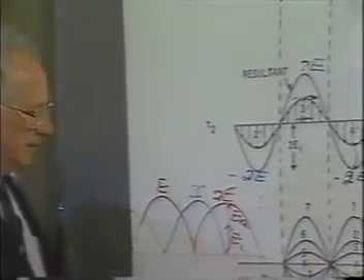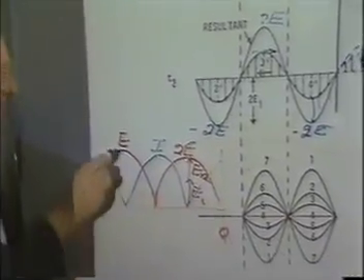What happens then if you have a resistance that is a pure resistance less than Z0? What happens to the voltage now? The voltage comes along the line, but instead of going up, the voltage has to go down because the resistance is smaller than Z0. It can't support that voltage. So the current goes up and the voltage goes down. Notice if it's a pure resistance, it will go exactly in phase, won't it? Notice this. This is exactly in phase. This is exactly out of phase. Exactly out of phase, exactly in phase.